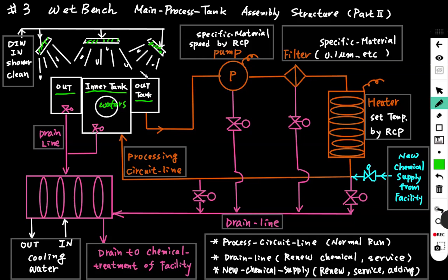and during the maintenance period, we drain out completely the chemical, and then empty the tank and start the DI water in, shower clean the DI water in, and use the nozzle to spread DI water to clean the tank.